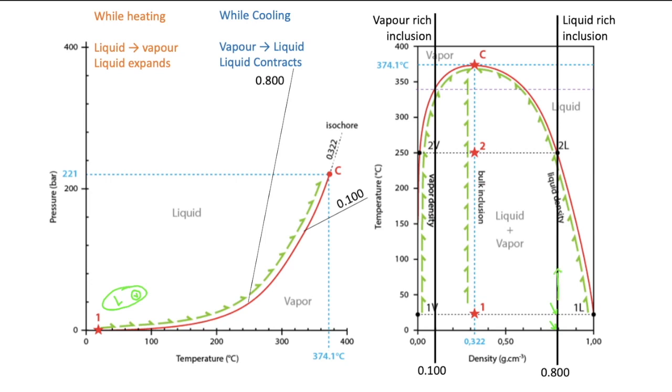Both liquid and vapor. But you see again, if you apply the lever rule, this length at any temperature, let's say the temperature is this, indicates the amount of vapor which is present, and it keeps on decreasing. As it reaches 250 degrees Celsius, at this point in the figure, the amount of vapor is very less. The whole length now corresponds to the amount of liquid which is present.